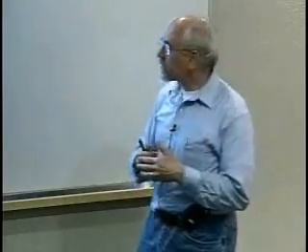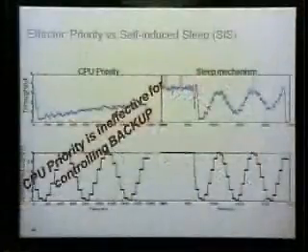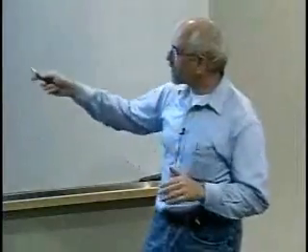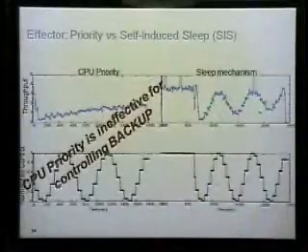What you can do is run the controller faster. Instead of doing this every minute or so, you could try to run it every second, but then your overheads are huge. And there's a lot of other dynamics. You may start seeing some scheduling dynamics that cause more of a skew, so instead of these peaks lining up, you might see this shifted more to the right. That's the kind of trade-offs you face in this sort of design, and it goes back to the discussion about sampling times and control frequencies.